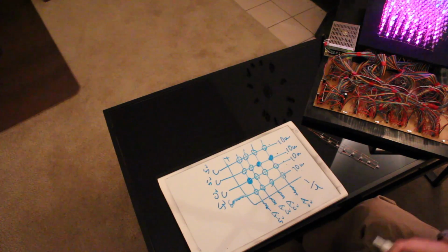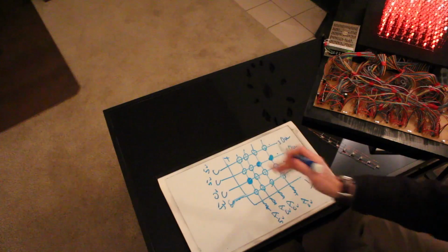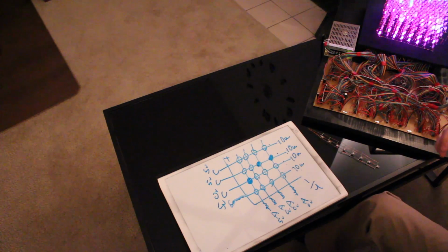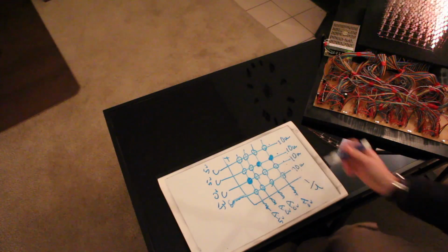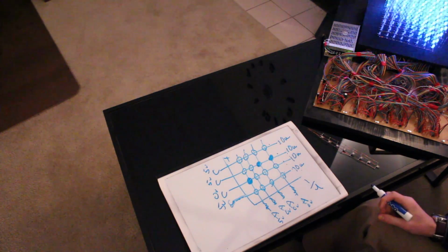Beyond what is your typical ratings, you lower the resistor so you're actually pushing more current through. So when it is on for that 10 microseconds, you're slamming them hard, and you're still safe because it's only going to be on for 10 microseconds. You're only pulsing it just for 10 microseconds.